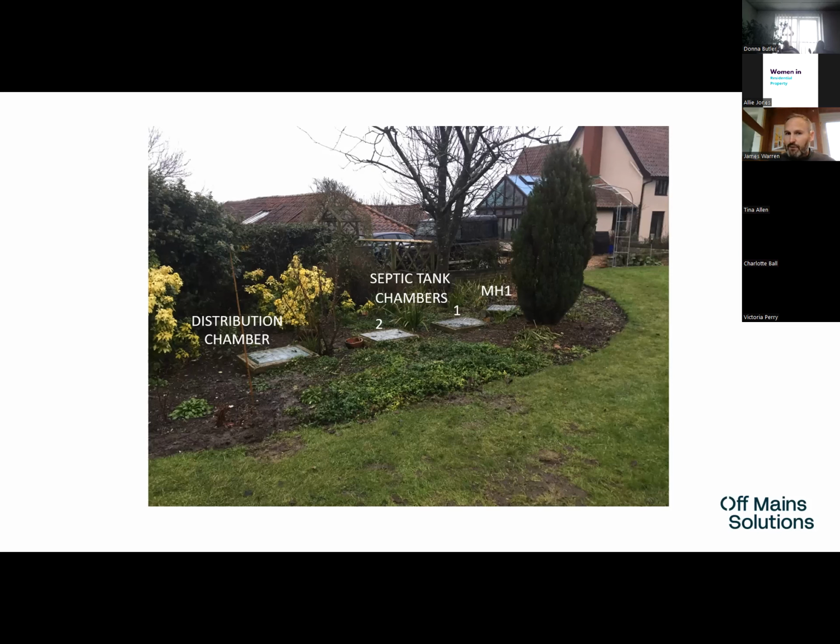If you can't see any crust and you're just looking at liquid inside that tank, that's actually a red flag. That means that water and the waste, everything, is being pushed through that septic tank before that correct and natural separation process has occurred.